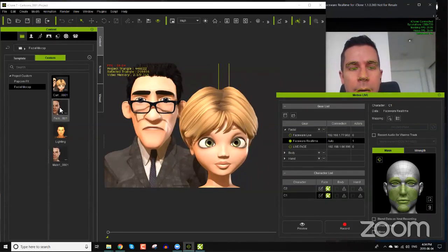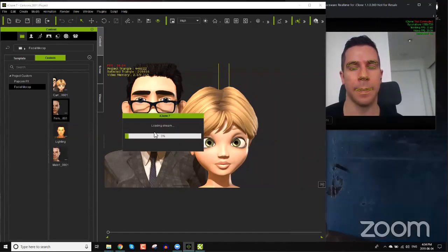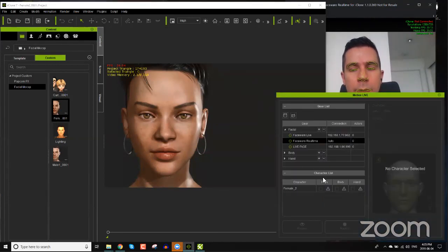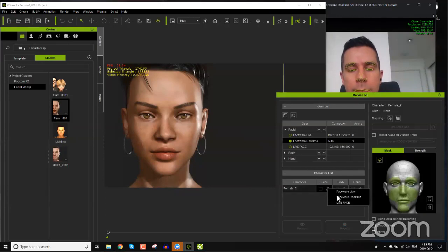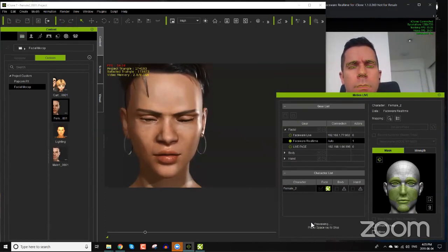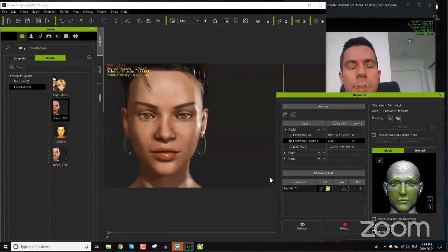And let's load in that other project again here, and we're going to talk about recording and editing, okay? I like the looks of this character. Okay, load up there, buddy. All right, so once this loads up, we'll talk about the recording and editing, which is all the fun stuff. All right, there we are, same character, and plugins, Motion Live, and we need to connect the FaceWare real time, and connect our face to FaceWare real time. Okay, and preview just to make sure. Okay, good enough for me. Actually, I'm just going to go ahead and recalibrate one more time.